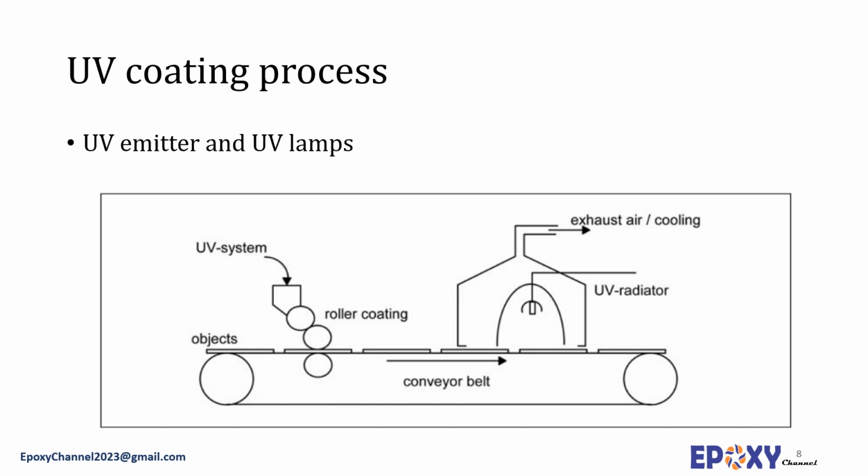However, some of the ingredients of UV systems could be a health hazard. UV light leads to the production of ozone, which also has to be exhausted carefully. Moreover, heat may evolve during the UV curing, which may promote the evaporation of the UV system contents. Because of their viscosities, solvent-free UV systems are often used in an automated continuous roller coating or a curtain coating of planar objects, wood plates, laminate sheets, foils, etc. And there are only a few instances of spray applications.